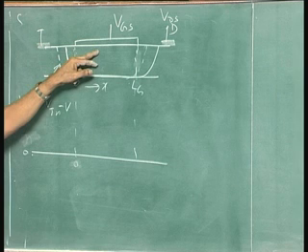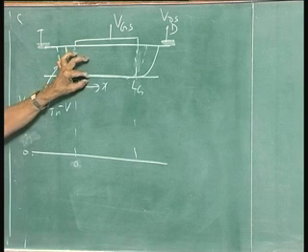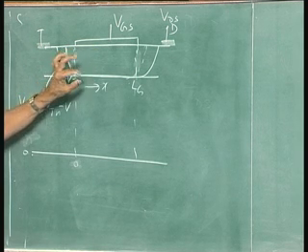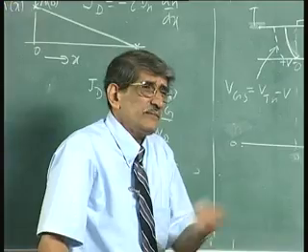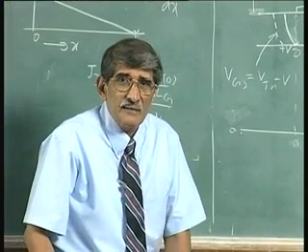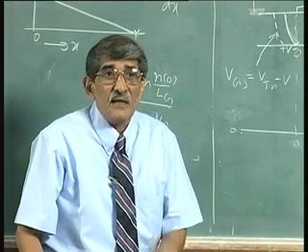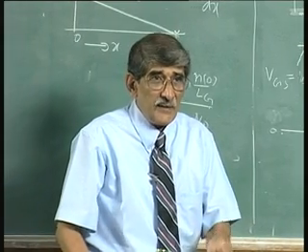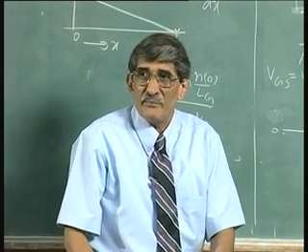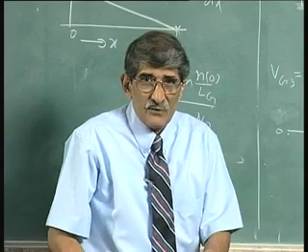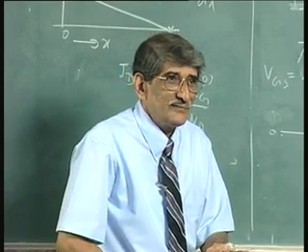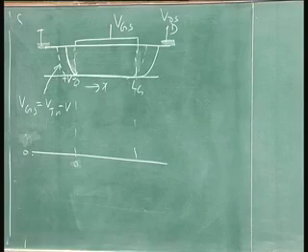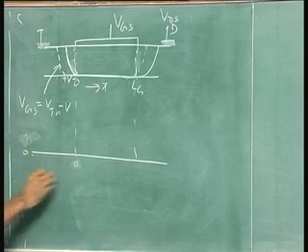It goes way down to 0. So, what we are talking of is a very thin layer, a Debye length. How much is the charge? We have to worry about that, because we will still be having microamperes of current. You may not worry about one device, say 1 microampere or half a microampere, but in integrated circuits, if there are hundreds of such devices which you believe are off, all those currents add up, and there is power dissipation. That is why you want them to really turn off, with a very low voltage difference. So, now what will be the potential difference?